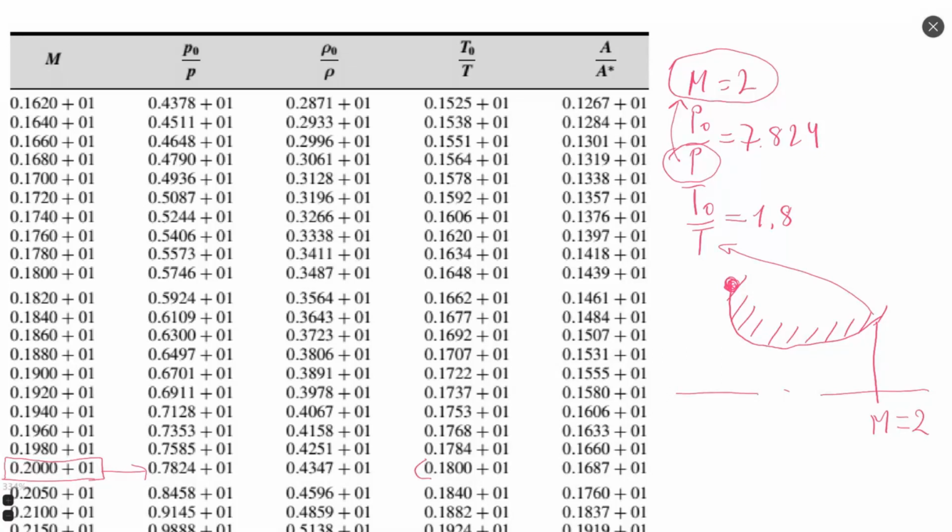Then we need to estimate which Mach we were in this section, and then using a table according to the Mach estimated, I can see the flow properties according to isentropic relations. Isentropic relations are not valid for all possible cases. They are limited to isentropic flow.